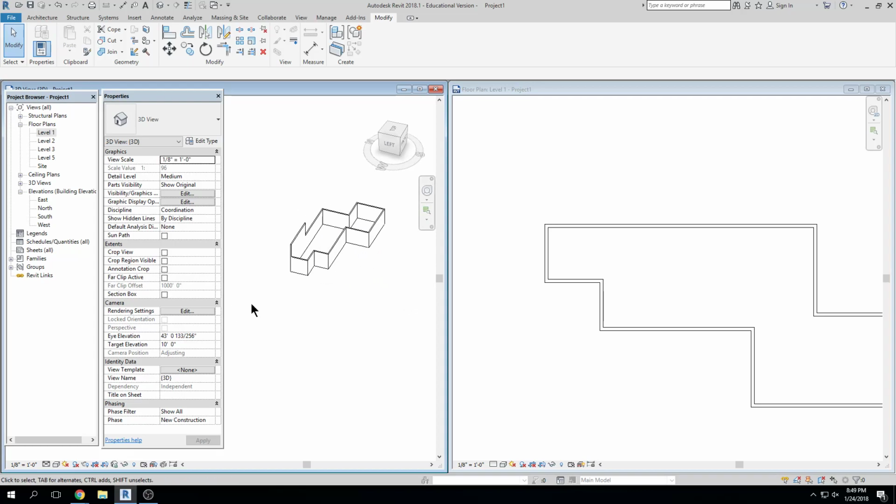All right, so does the idea of defining walls and levels somewhat make sense? Yep. So, a question for those interior walls. Let's say the basement interior walls. It goes from the top of the slab to the bottom of that joist, and then we have the ceiling and whatever. Yes. So mark that datum point? Yes. The bottom of that, so that we can tell it to go from this level to this level?